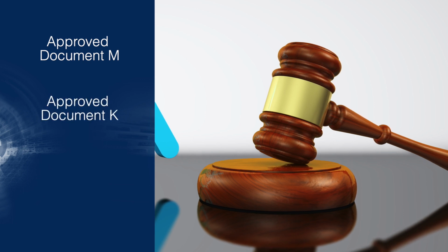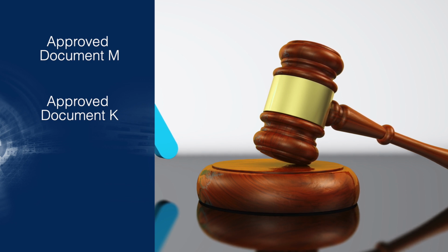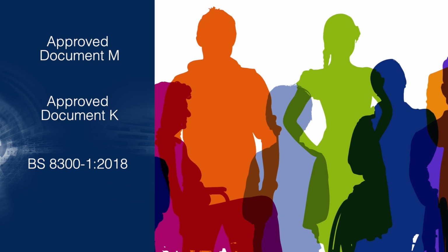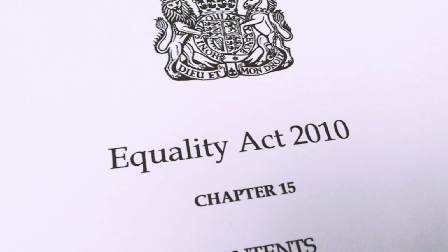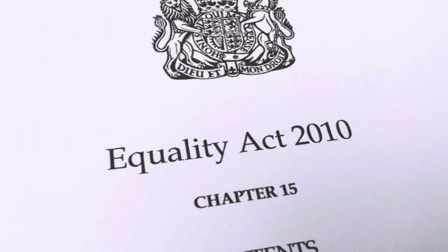Approved Document K addresses safeguards against falling, collisions and impacts, encompassing features like stairways, ladders, ramps, guarding and vehicle barriers for various building types. BS 8300-1 serves as a code of practice pertaining to inclusive design, strategic site planning and building layout. Meanwhile, BS 8300-2 focuses on designing an accessible and inclusive built environment. It is important to consider all these components in light of the Equality Act 2010 to ensure compliance with legal requirements and promote inclusivity.